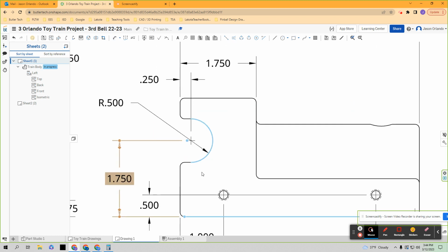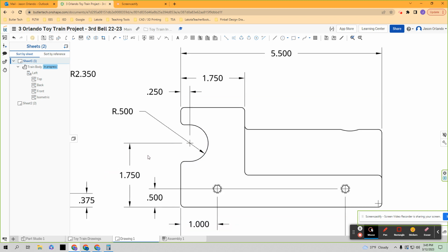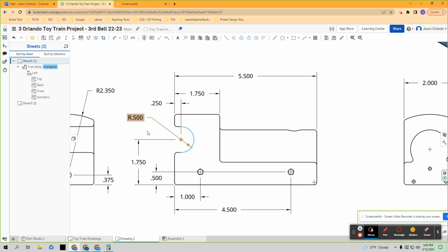Okay. Now you may think, do I need to know where this ledge is, or the height of that? And I don't, because I know the center of this feature, and I now know the radius, so this distance here, I know it's a half. I didn't explicitly state it with a number, but I would come down from that center mark a half inch. So from the 1.75 coming down a half inch, this would be at 1.25. And if I went up a half inch, I'd be at 2.25. So that's actually known with a little bit of math.